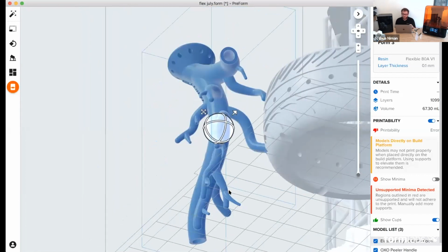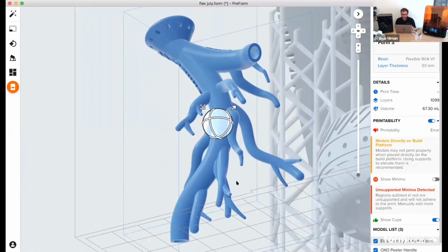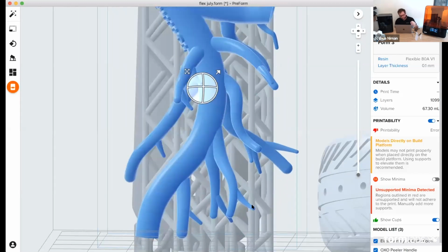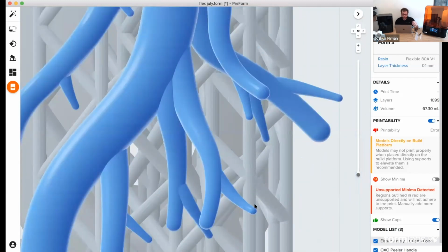If you were doing that in a soft material, and there's no reason why you would, you're going to run into trouble where those two arms of the Y meet. Because of the peel forces involved, the softness of the material, and these very far apart anchor points, you might have a tear there, just like breaking a wishbone at a Thanksgiving turkey. So you always want to avoid geometries like this.